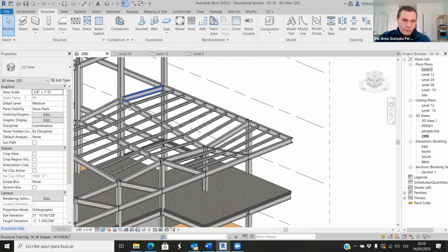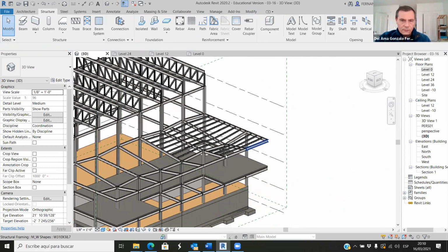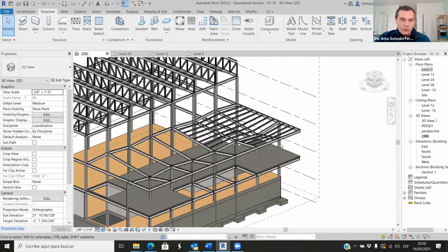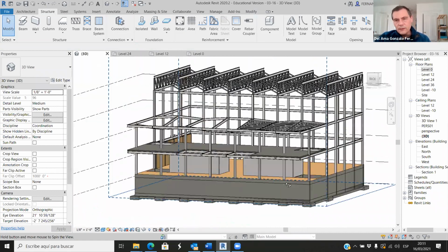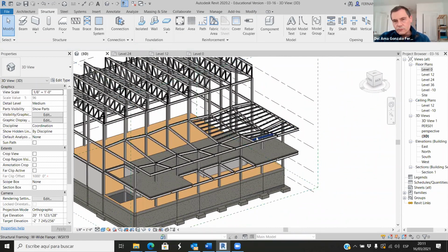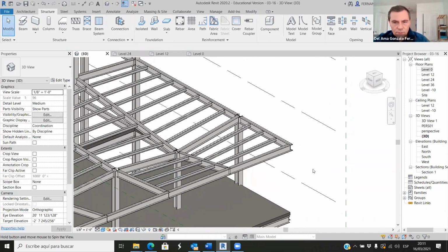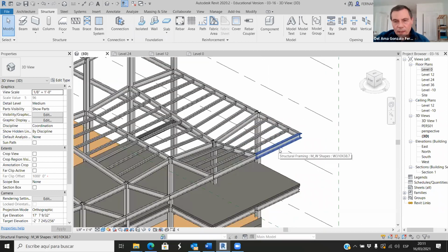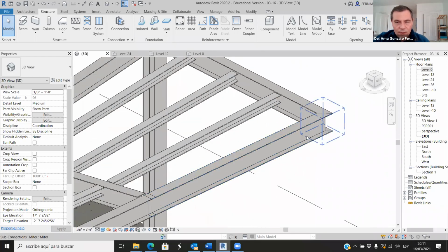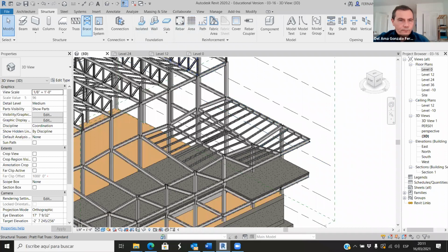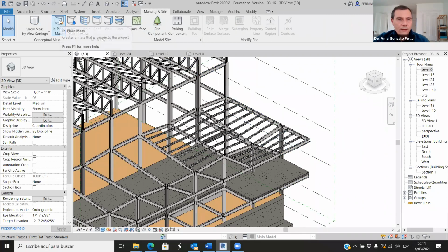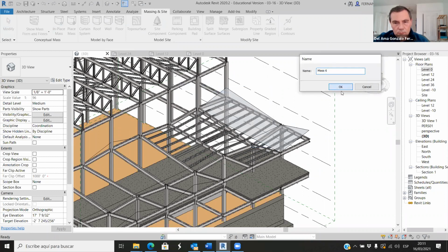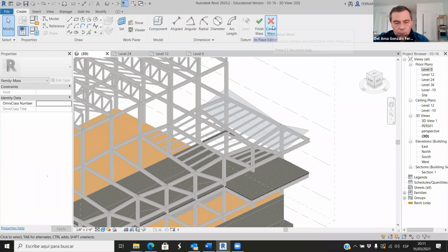Okay, so we are going to create a roof here, and then another roof there, and then you will have to have different roofs. Well, you can mirror because this is symmetrical, but at least these first two roofs, we have to create. So the only way I know, maybe there are other ways, but if I had to do that, I would use the massing, the in-place mass. Well, I did this before.